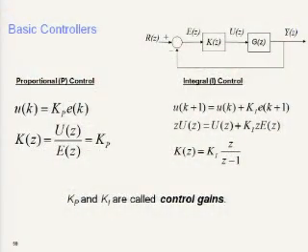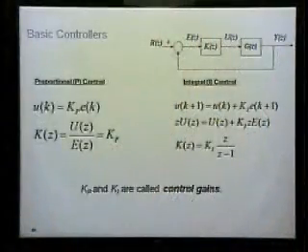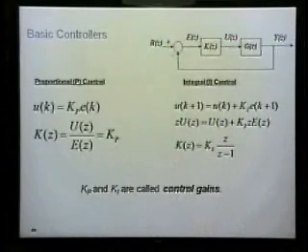All right, so the way I'm going to start here is to talk about some of the basic controllers, and we'll see how they behave. We've seen this proportional controller, the one we had in the early example. Here's the time domain equation. We know exactly what this translates to in the z-domain using the material we had before lunch.